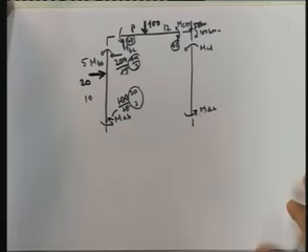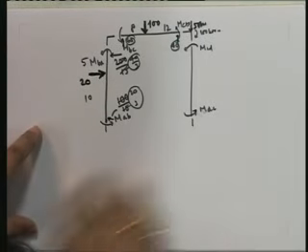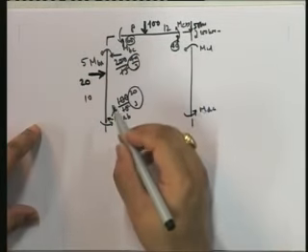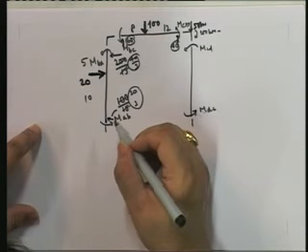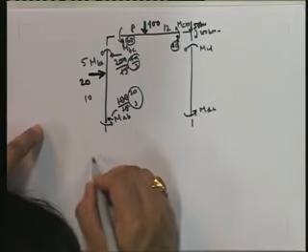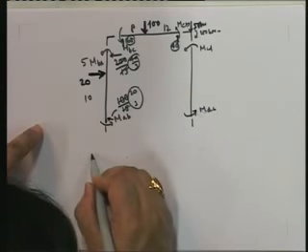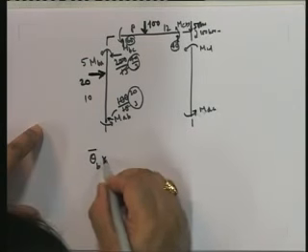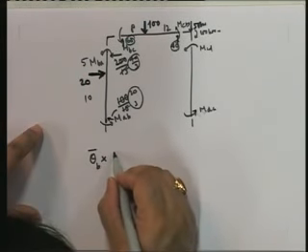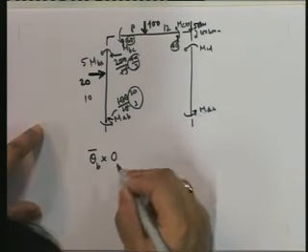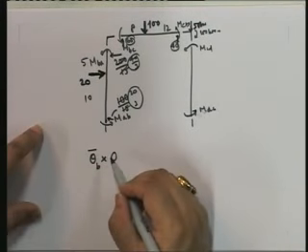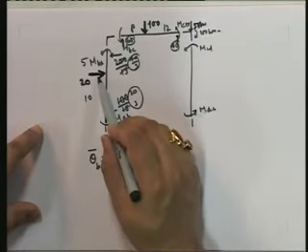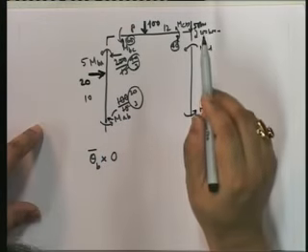So now what is my virtual work equation? I'm going to put theta b equal to 1. So theta b, this is my virtual displacement pattern. Theta b into the moment at b, which is 0. This is the external work done. I'm calculating all the external. Note that these I have translated, so member loads are never external. It's only joint loads which are external.